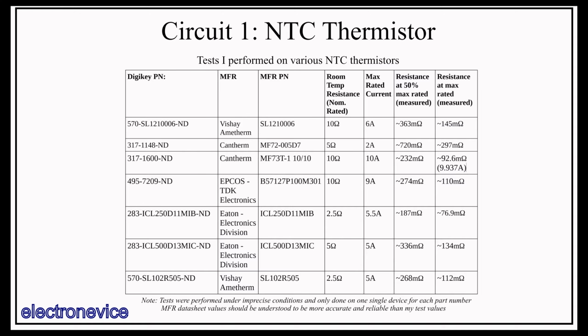It's worth mentioning that I lean towards the higher current options, as I tend to deal with projects that operate at relatively low DC voltage and have higher current. However, for projects operating at mains voltage, the currents tend to be much lower unless you have a very high power project involving a motor or some other power-hungry device. The max rated resistance at load can be much higher for a lower current project without causing problems, and thus the NTC Thermistor Soft Start just generally works better for circuits at lower currents.